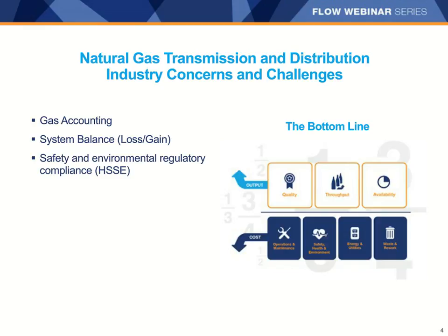Gas has to keep flowing in many instances to meet contractual line pack commitments and to avoid the safety issues that would arise if the flow of gas were to be cut off. For this reason, availability and continuous functioning of measuring instruments is crucial in order to avoid the unpleasant consequences that occur when a meter stops working and gas has to be allowed to flow by the meter unmeasured.